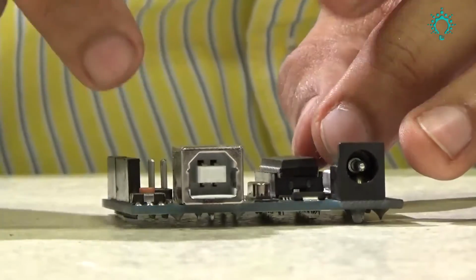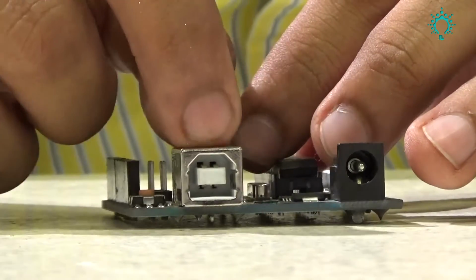There are a lot of requirements where we want to communicate between Arduino and our PC. For example, you want to create a program in which you want to switch on the lights or the fans, or do anything with your PC. If you press keyboard button 1, you want a tube light to be on, and if you press button 5, you want the AC to be on. That can be done. How? Arduino is connected to the tube light and the AC with the help of a relay, and you can connect your Arduino and laptop through this USB port. So this is the second part.